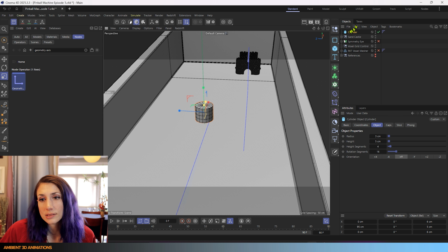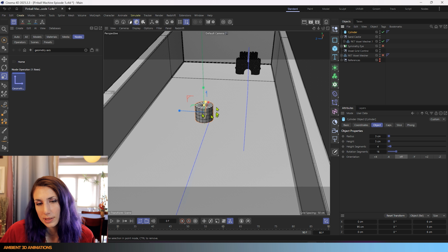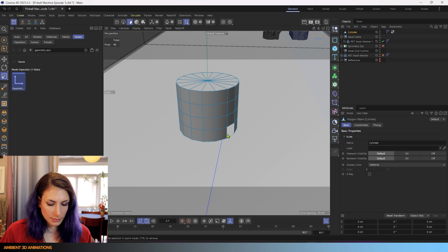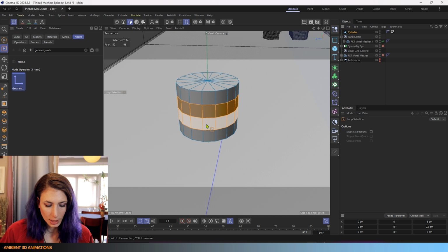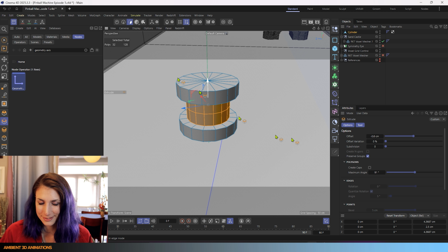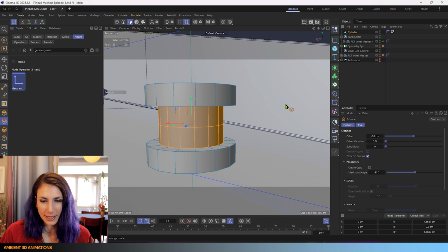And there we go. Something that I did want to do is I like the idea of putting little seashells on top of the bumper, so I still want to do that. For height segments, I think we'll be okay with this probably. And I'm going to hit the C hotkey to make this editable. I'm going to go into polygon mode, use UL, select these two. We're going to use MT, and this time we are extruding inwards, but you'll see we left our preserved groups off, so I need to hit undo, make sure to have that turned on, and then do it again. So that time it looks much better.